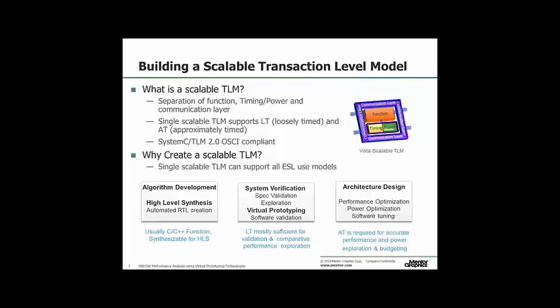It also allows you to take functional models, maybe existing C++ code, wrap them very easily around the communication layer, and then add timing and power policies on top of that to automatically generate the performance aspects of the model. This eases the mechanism to create accurately timed models without having to hand create lots of SystemC, lots of complicated timing and power code. This can be abstracted away using this mechanism, which we call timing and power policies.